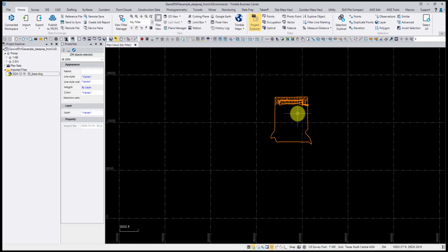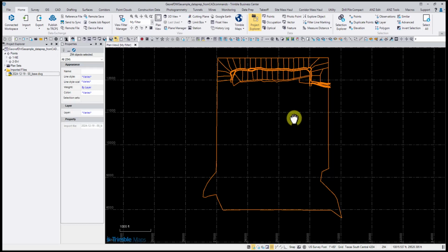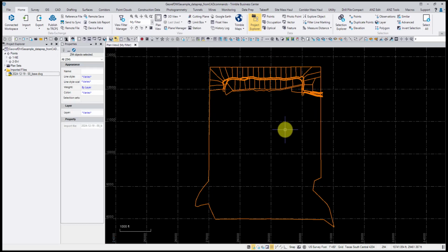into the area. Now this is where the Trimble Business Center defined views come into play, because it's a way to bookmark an extent and think about how that could be helpful when you're georeferencing in a split screen manner, where you're looking at the CAD drawing on the left and the points that you're georeferencing to, or the control, on the right. And leveraging the defined views makes it much more efficient.